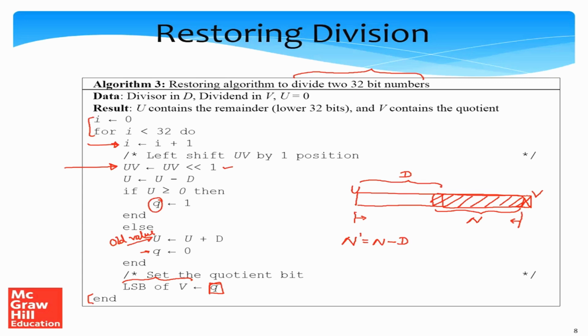Mind you, the divisor as compared to the beginning of this number is shifted to the left. How many positions? This entire distance is n bits, and this distance here is 1 bit. We have ignored these bits because we have left shifted anyway in this line. So as compared to the beginning of where the dividend starts, the divisor is n minus 1 positions to the left.